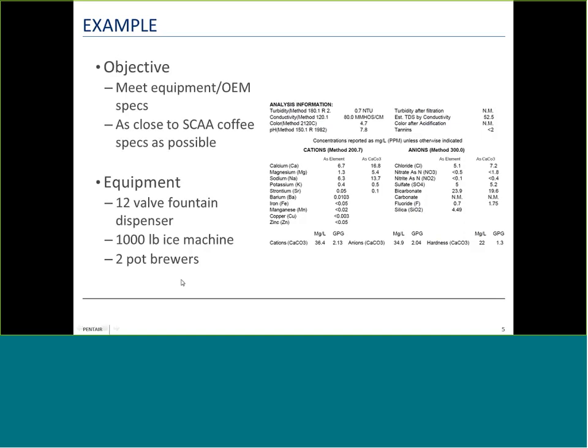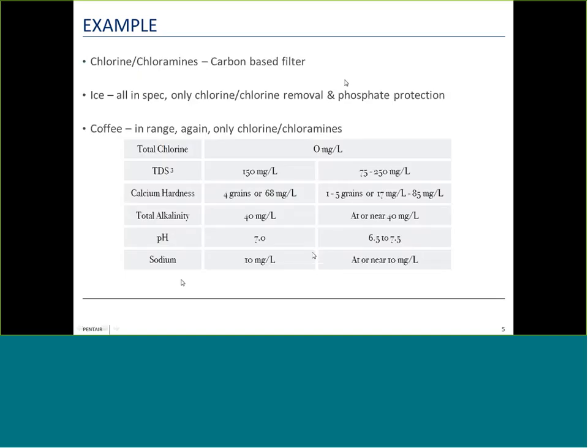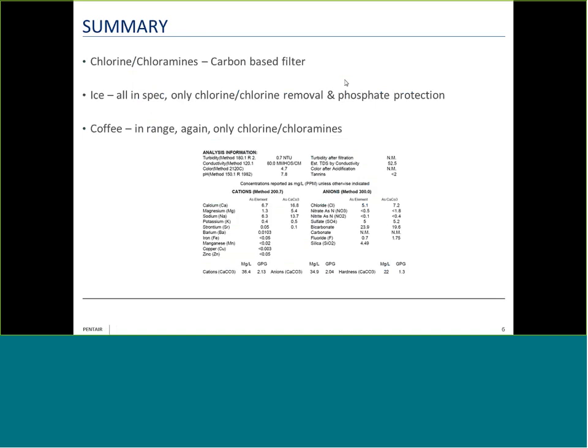Most manufacturers of steam cooking equipment have their standard at 60 or below, most right around 30 parts per million of chloride. And the reason for that level of chloride is that the oven should make it through its warranty period without exhibiting any corrosion or any significant damage that would be unacceptable to a customer. So there's a cost-benefit selection done there. But as we increase temperature, we have to be aware of the impact of chloride on the stainless steel of our cooking equipment.